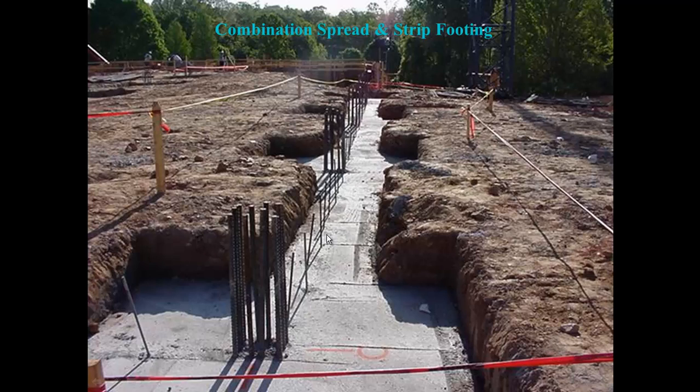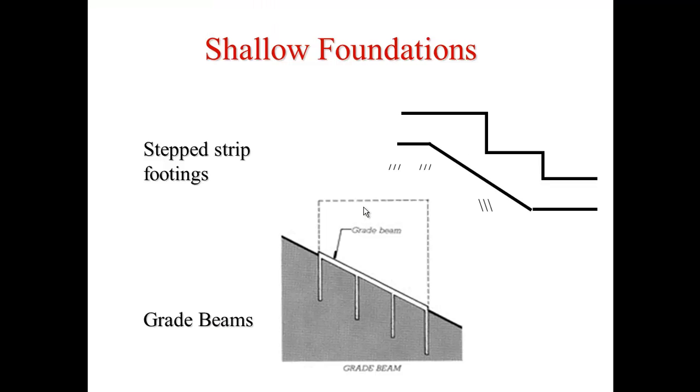So we can see our reinforcing steel coming up that's going to lock into the concrete wall, but also these column locations that are going to lock into these areas where we're going to have a steel column probably on a base plate that's going to support the sides of the building. So this area is not very deep, so it's probably in a less frost-prone area, so not a very deep foundation.